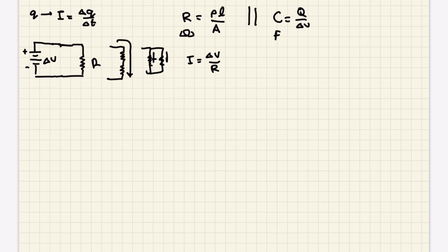So the capacitance is just a set property of a capacitor, just like resistance is a set property of a resistor, and this is Ohm's law that relates resistance to the current flowing through. This is basically the same thing. It's an analog of Ohm's law. It says that the amount of charge that can be stored on a capacitor has to do with its ability to store charge, which is its capacitance, and the potential difference that's between them.